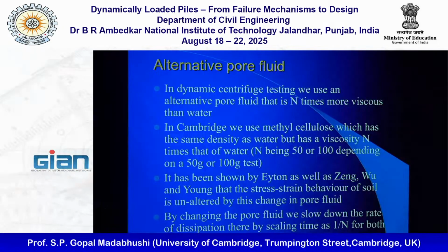So because we change the pore fluid, the permeability effectively reduced by a factor of n, which means when the pore pressure is building up, say I applied a sinusoidal motion like this, and I'm looking at the pore pressure, it will start and it will do that, and after the earthquake is finished, it will start to dissipate.